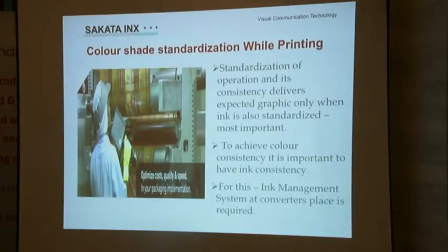So for that, what happens, like spot colors, there are many spot colors. These keep on changing. Sometimes you have taken, let us say, certain yellow, certain magenta, and the ratio was, let us say, 80-20 to mix it and make it red. Sometimes you are taking yellow and magenta from a different supplier, which is not matching to that particular ink. So then the shade will change.